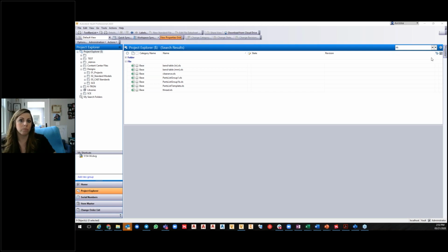So does that change sit within the task list or under the SQL stack within Vault? It sits on the task list, but where it really lives, the most important place, is that the task list is just a way for you to execute those things if you wanted to do them and build them up later. All of that data is being concatenated from the project database. It's that Access database file sitting in the background that's building out all of the project database information so that it stays synced. Your true information to everything within your drawing is actually living in that database.